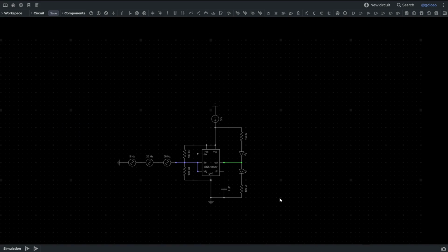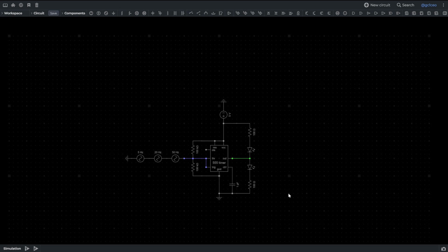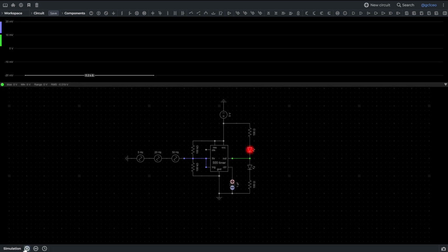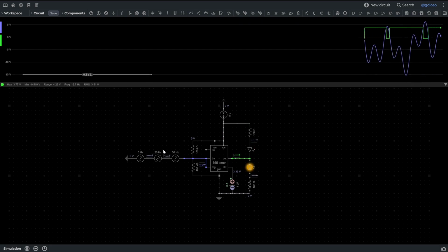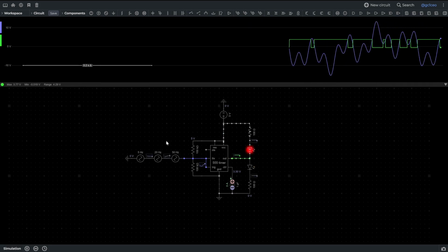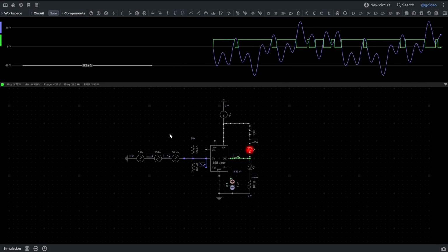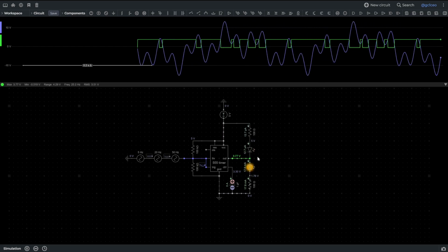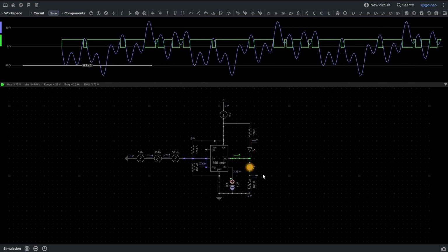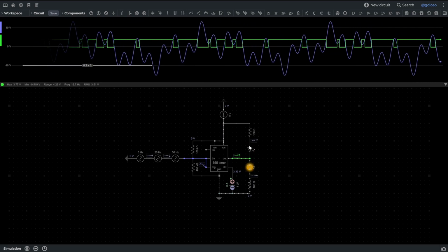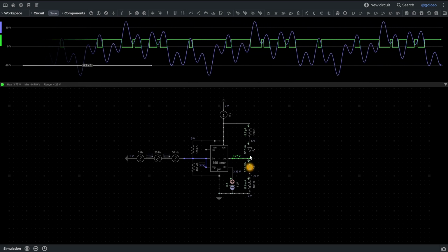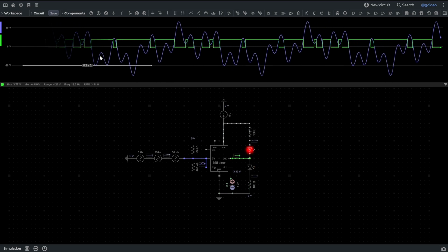All right. On every circuit here, and this is effectively a Schmitt trigger made with a 555 timer. We basically have an analog signal. I made it kind of dirty here. We've got an upper and a lower threshold here. I can't remember which one's which. I think red should be upper and green should be lower, but it may have those reversed.